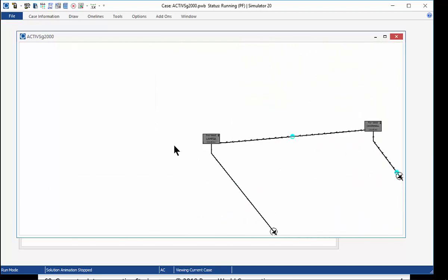So we'll be interested in finding out through this process whether we have enough transmission capacity to deliver power from that point to other points in the system, and what that does to voltages and what it does to the contingency overloads.